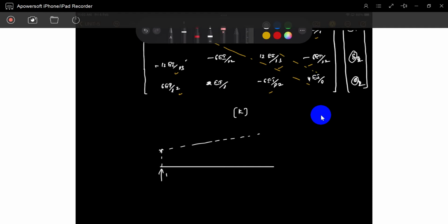Sir, it is not possible. Why, sir? There is no restraint. Okay, we have to release the forces. There is no force developed, only deformations developed. Okay, if you apply a unit force, here one delta, one rotation, here another delta, another rotation. It is generated, but there is no stability here. You can't develop it. So that's why you never see a flexibility matrix.